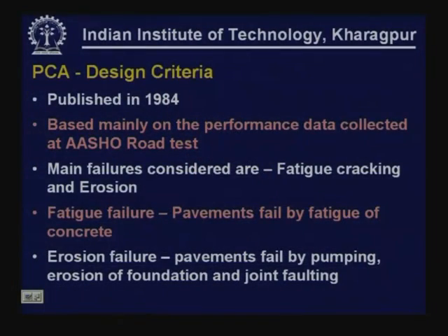So PCA considers two types of failures, fatigue cracking and erosion of foundations. Fatigue failure is the one in which the pavements fail by fatigue of concrete. Erosion failure is the one in which the pavements fail by pumping. We discussed pumping in the previous lesson: erosion of foundation leading to formation of gaps below the slab and joint faulting, the joints being at different levels.